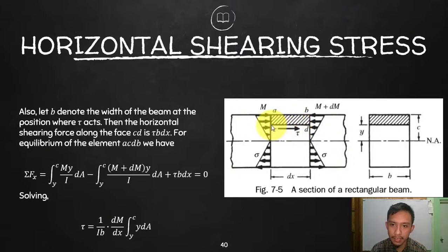So what is the area? This is the side of that CD, multiplied with the cross-sectional dimension, which is b. What is this distance CD? Let's say that is dx, since that is our assumption a while ago. So to make this a force, tau is multiplied by the area b times the length dx. So that is the area receiving, or resisting, your tau.